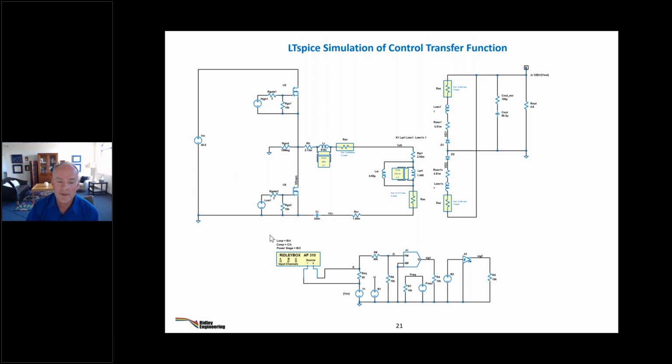Just take an analyzer. This is what you do in the lab. You take our Ridley box or you take our AP310 or whatever device you might have. We have built that emulator inside LTspice. So you just sweep through the frequencies, you put it through this frequency modulation device here. So you're modulating the frequency of the switching, and then you're measuring the stimulus to the output and making measurements of control to outputs of the LLC converter.